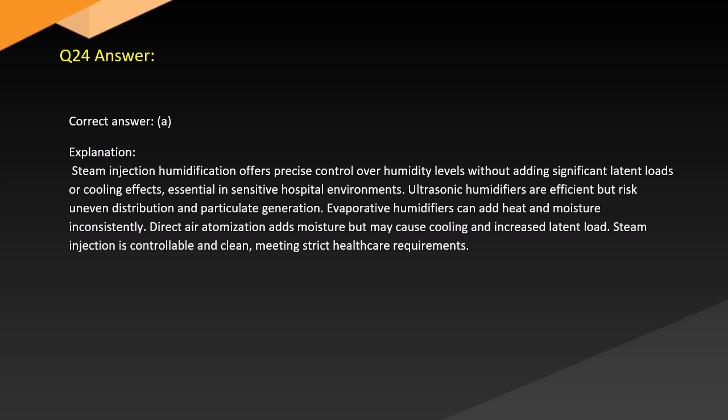Answer. Correct answer, A. Explanation. Steam injection humidification offers precise control over humidity levels without adding significant latent loads or cooling effects, essential in sensitive hospital environments. Ultrasonic humidifiers are efficient but risk uneven distribution and particulate generation. Evaporative humidifiers can add heat and moisture inconsistently. Direct air atomization adds moisture but may cause cooling and increased latent load. Steam injection is controllable and clean, meeting strict healthcare requirements.